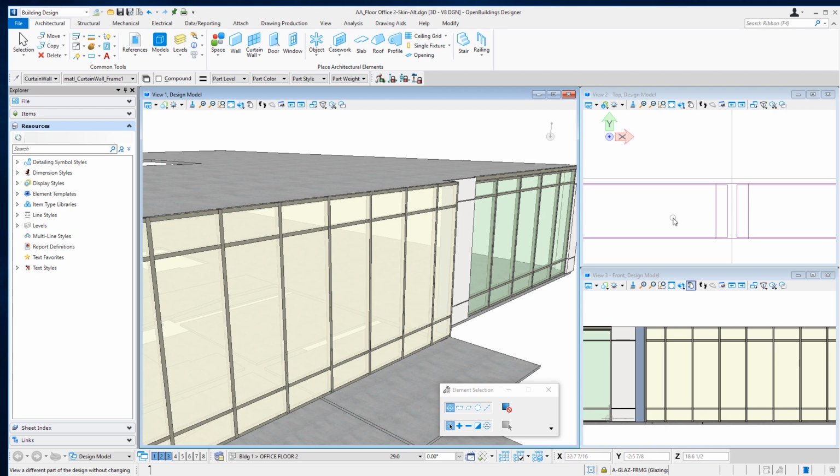So I created the profiles by creating variations on the standard delivered profiles. And I created the panel by simply creating a panel data group definition that was 4 inches thick and used a translucent part that I created, and then was able to place my system shown here.